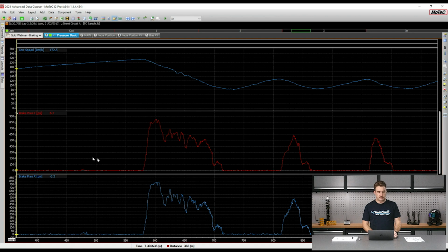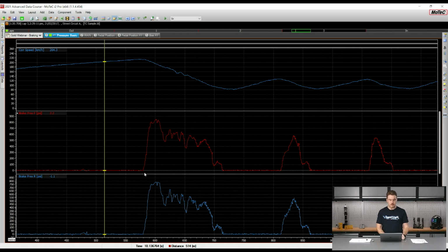So obviously what's happening here, we've got no action or very little action on the brake pressure as we move through this section. You can see on the speed trace, the car's still accelerating at this point on track. And then we see a relatively steep climb in the initial brake pressure, and that's happening both on the front and rear axle. So in this particular situation, it's a motorsport style pedal box, so you've got a front and a rear master cylinder side by side being operated by the same brake pedal. So it's two completely separate hydraulic systems, one for the front and one for the rear.